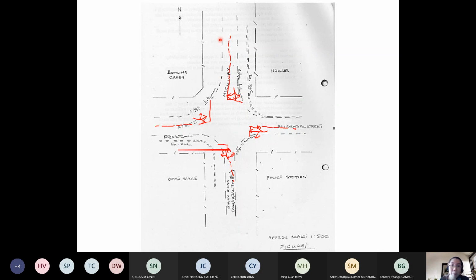But that means it is a delay for the user. The user has to come to a stop. Likewise for those who want to turn here, they have to stop here, make sure it's clear, and turn. So that means it is not convenient for these drivers. So how can we use channelization to give these two movements, the state highway users, a more convenient drive so that they can turn into north and north to west without having the need to stop?